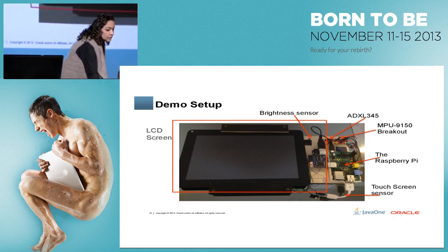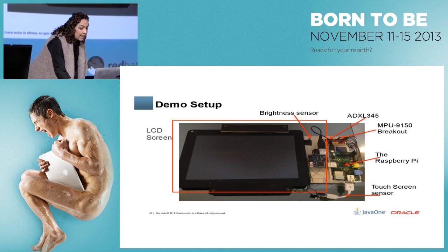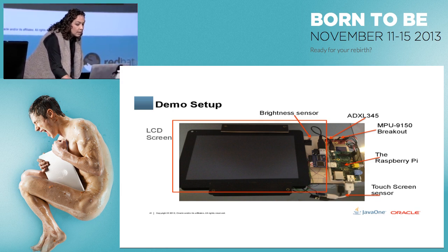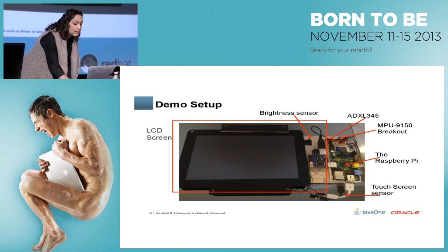If you pay attention here, this is the board for the screen that is HDMI connected to your Pi, and then here you have the USB that goes to the power of the Raspberry Pi. So in this case, the one that has power is the screen, and the screen itself is the one that powers the Raspberry Pi.